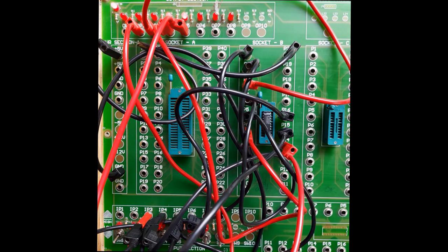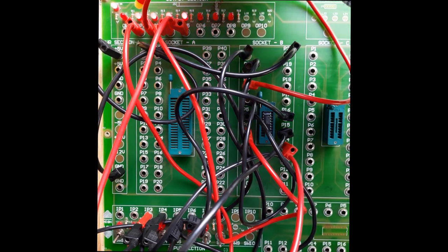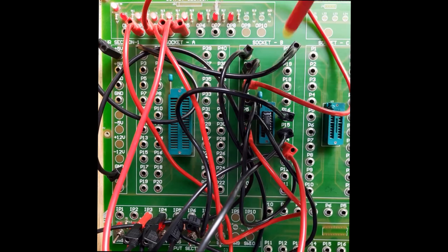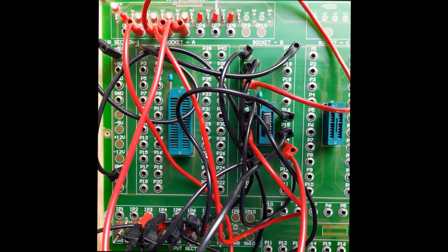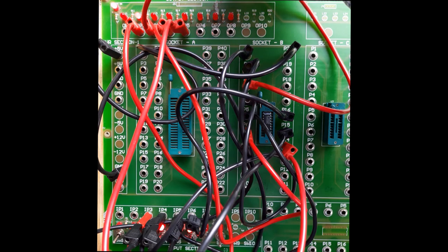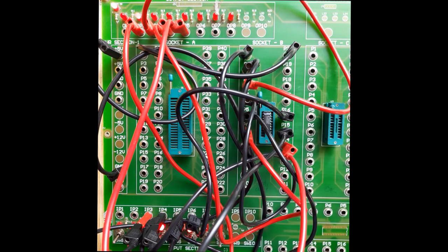Now we can check the input 1 0 1 0. In that case we require all LEDs to blink. Here you can observe all LEDs are high. Now we can check with all inputs high. As per the truth table your expected output is 1 0 0 0. Now only the first LED is high, and the remaining 3 LEDs are 0.